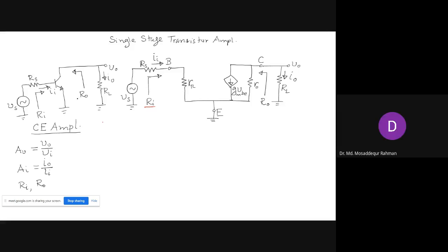The parameters that we are trying to determine are the parameters for the amplifier, right? Yes. We don't say transistor or base emitter, we say the parameters for the amplifier. What is the input resistance for this common emitter amplifier? The amplifier includes not just the transistor but those resistors and capacitors, everything together that makes the amplifier.